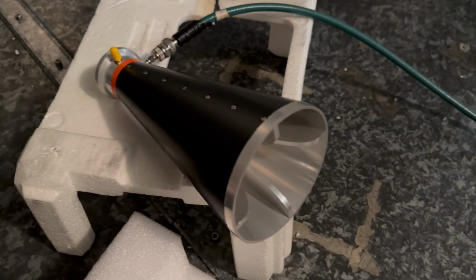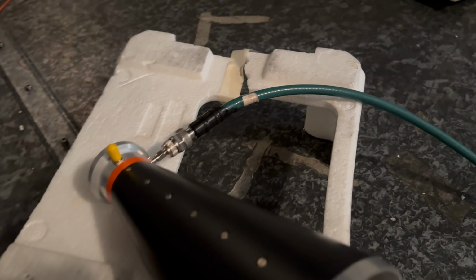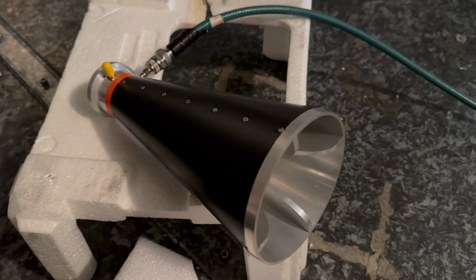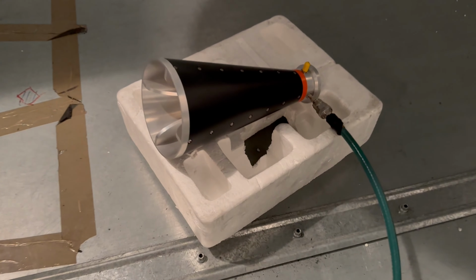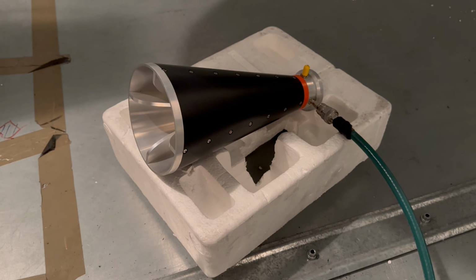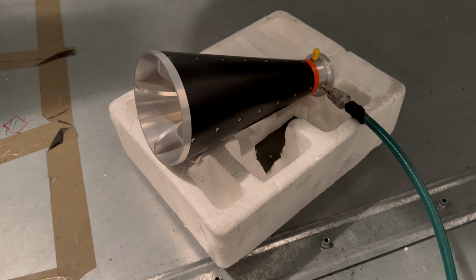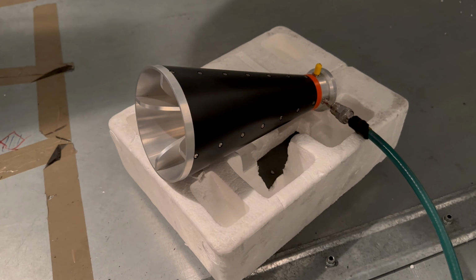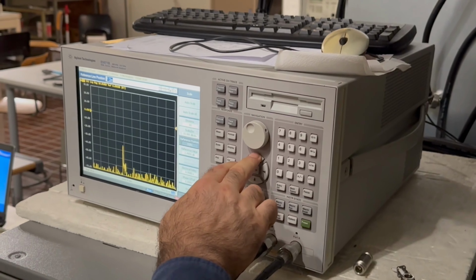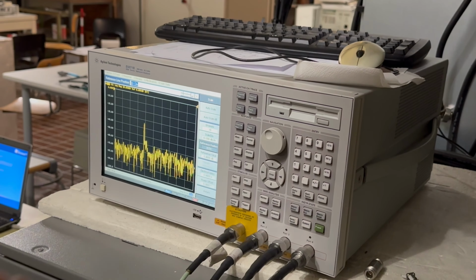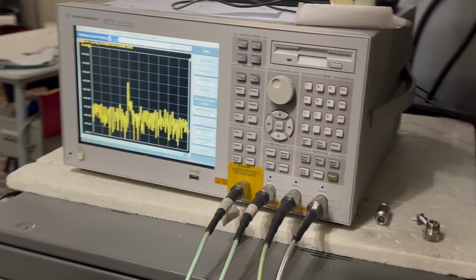So then we reconnect these dual polarized antennas back, and we have two antennas in this setup facing each other. So we want to see the line of sight in a PDP, power delay profile, so that we should see a spike, a tall peak. That's the arrangement. Okay. So I think that this pulse is a direct pulse.